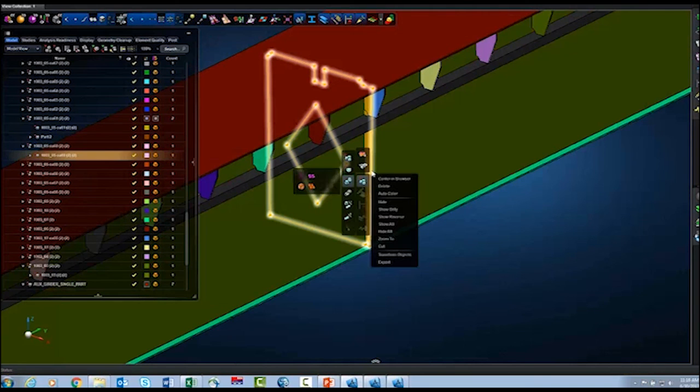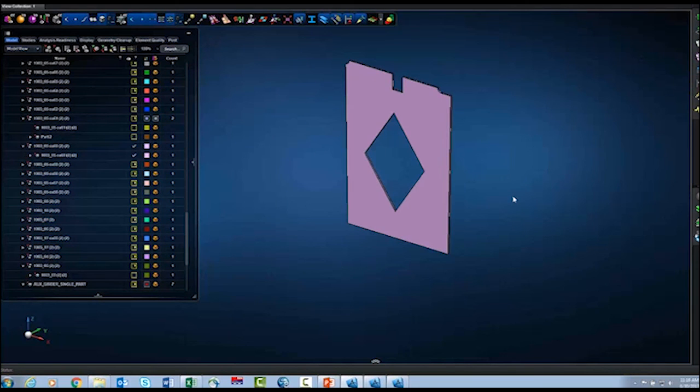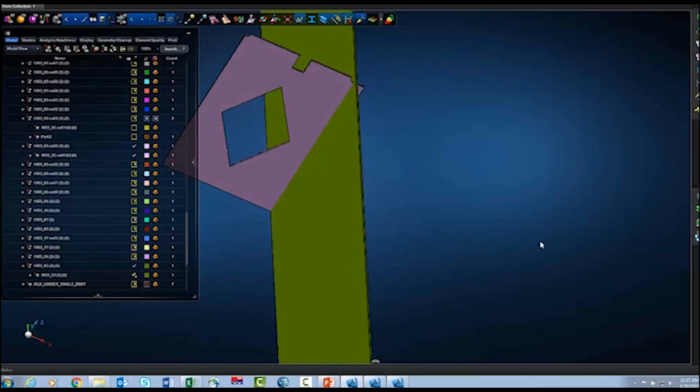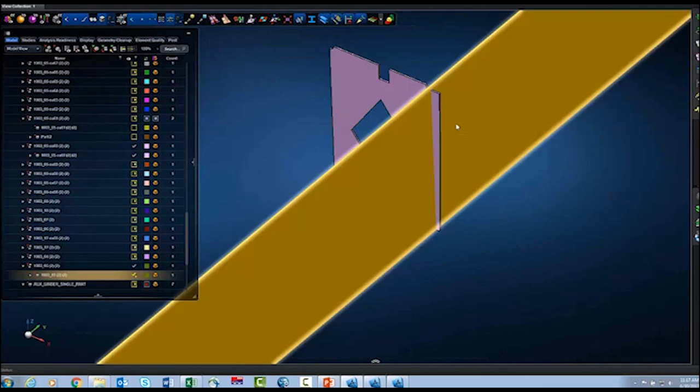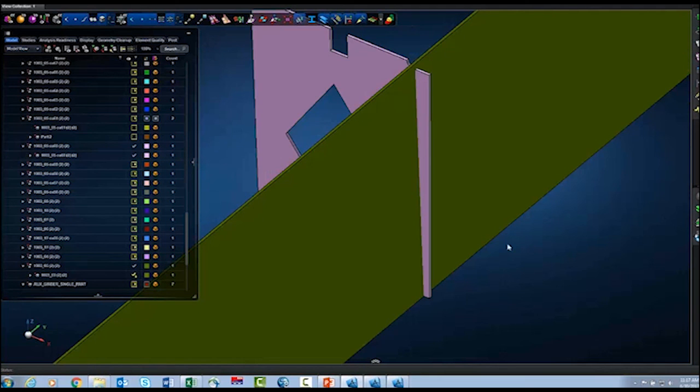And this can happen because perhaps you get distracted. You're working on the model, you leave your desk, you forget where you were, and in the end, you overlook this. And many times, because the structure has so many parts, you don't even notice. The guy that's going to notice is the guy that's got to do the finite element analysis model of this, because this will never do for him. He's going to want to fix it up. So this represents dirty geometry.